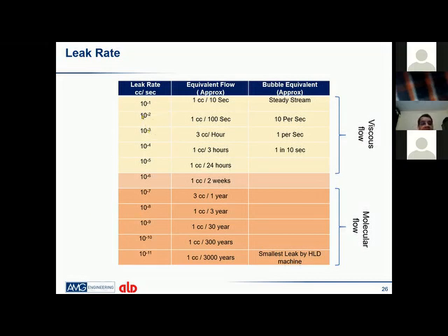But in the industry, 10 to the -3 is a very standard leak rate which everybody asks for, for old furnaces also. And when the furnace is new, 10 to the -3 is the leak rate which everybody is looking for. You can correlate and get some physical appearance also, like when you say 10 to the -3, what is the leak level and how big is the leak itself. Since a leak is nothing but the flow of gases from inside to outside or from outside to inside.